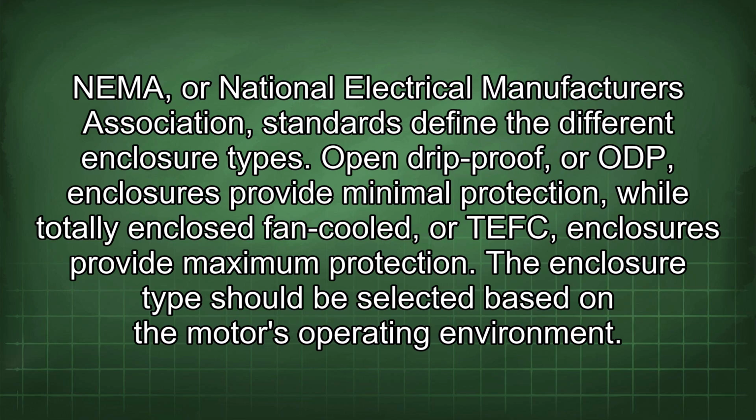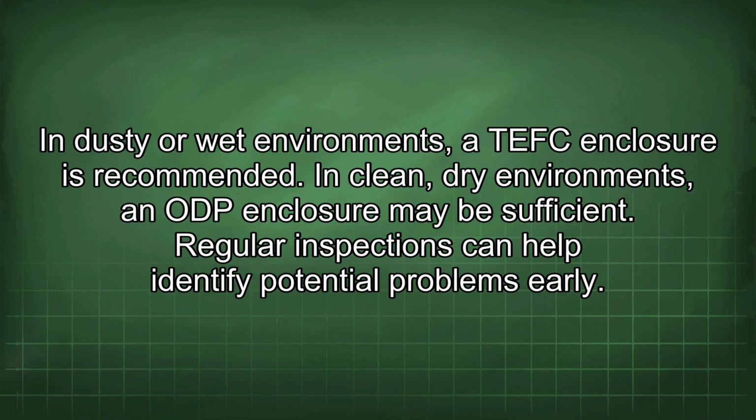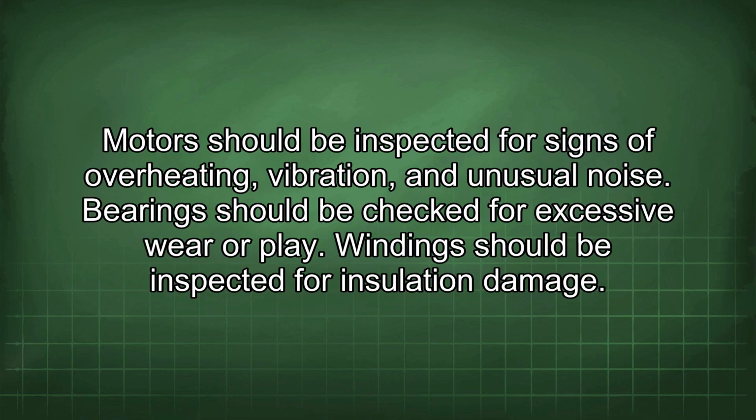The enclosure type should be selected based on the motor's operating environment. In dusty or wet environments, a TEFC enclosure is recommended. In clean, dry environments, an ODP enclosure may be sufficient. Regular inspections can help identify potential problems early. Motors should be inspected for signs of overheating, vibration, and unusual noise.